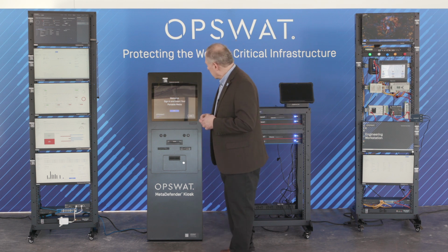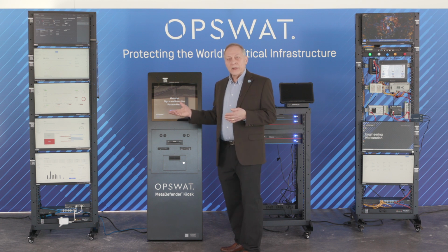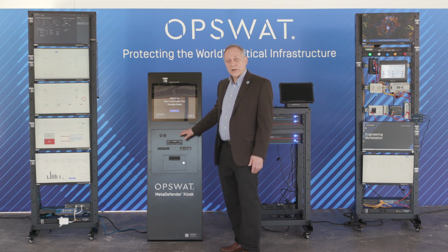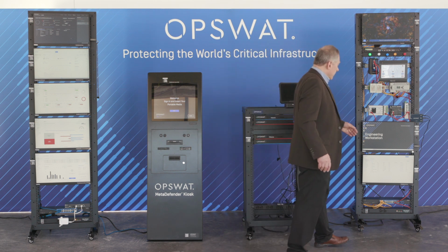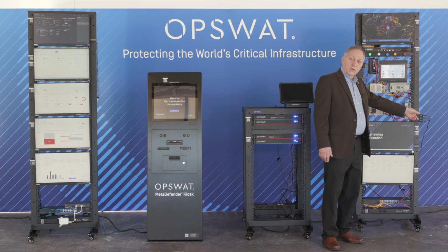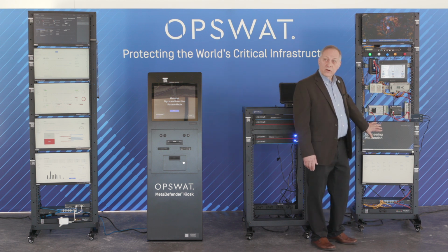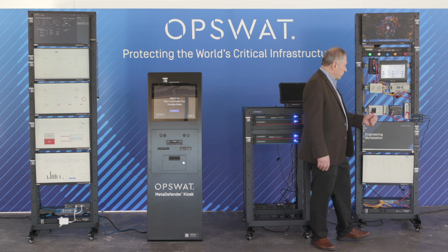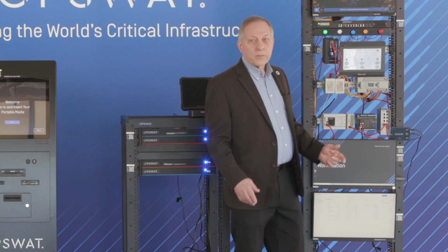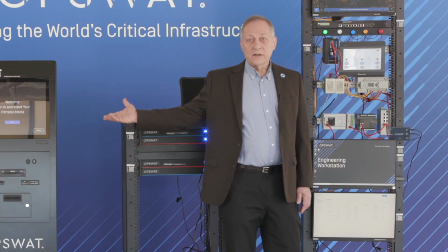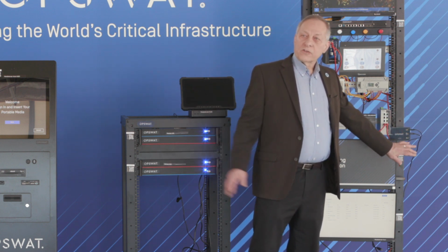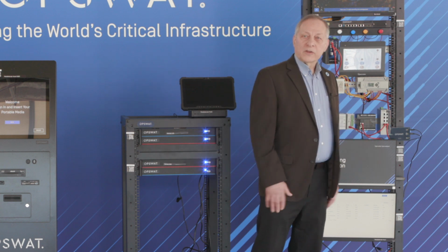So for example, you may permit USB media from the outside to enter your OT domain. You would scan the USB key here, and then in concert with our USB firewall product, or the media validation agent software that we have running on the HMI, you would insert the USB here and update your HMI. If the USB key was not scanned, it won't mount. So this technology prevents unauthorized USB keys from being mounted into your OT domain.